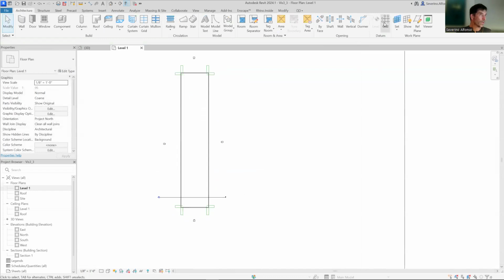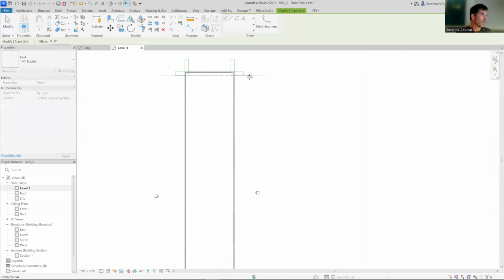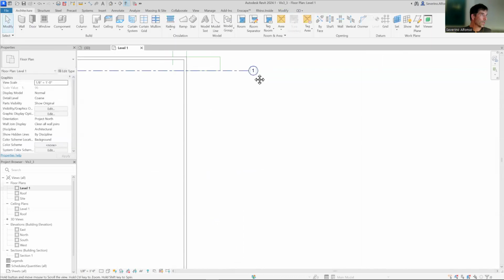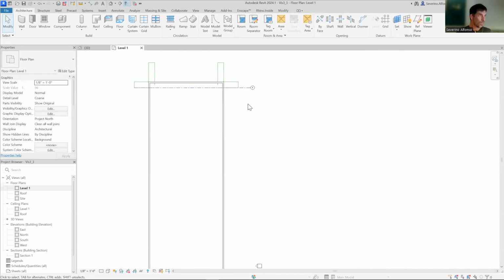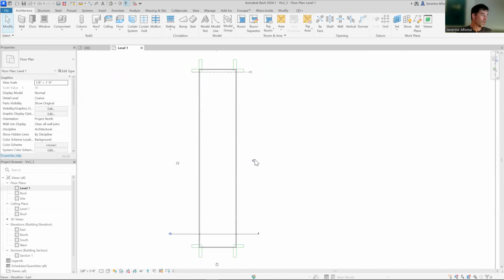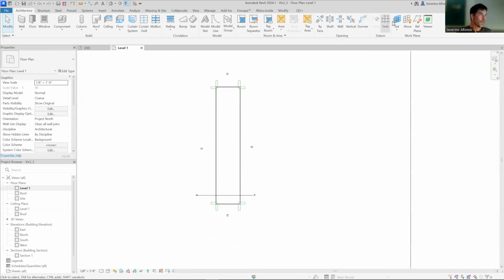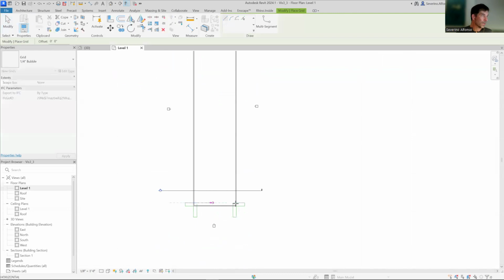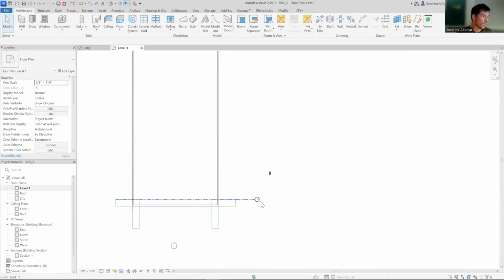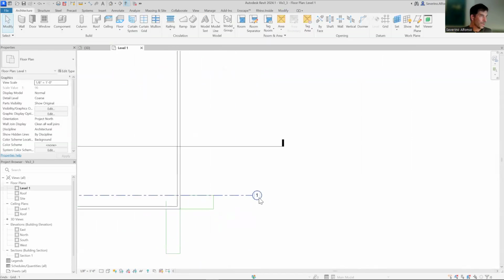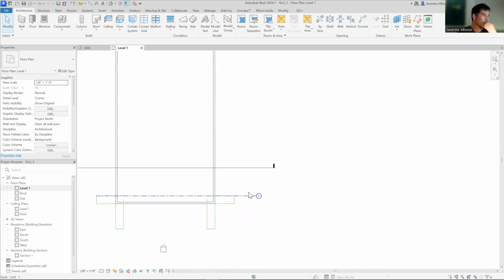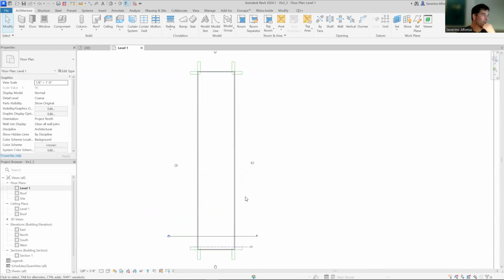I'm going to create the first grid. That's going to be from this point coming out. The first one typically is number 1. So, depending on the conventions, you typically go with number 1 on the bottom going up. So I'm going to go Control-Z, select the grid, and click here and make that the number 1. Only if you do Control-C, you will have the 0.1 here. So we could just start copying, I guess, 18 units if we count the sides.